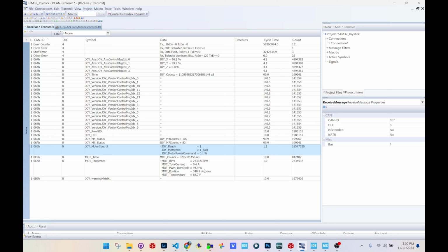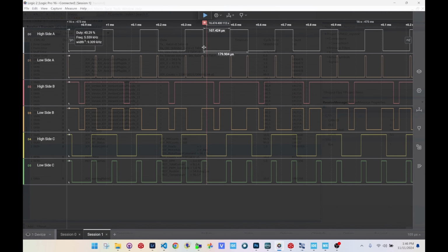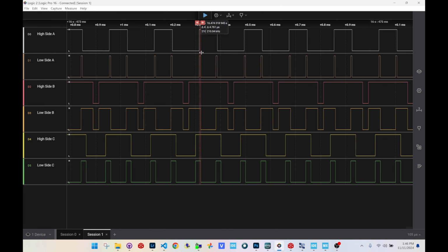I'll now show some of the signals on the oscope that are used to drive the motor. These signals are generated from the STM32H7 and used to drive the H bridge. These PWMs are generated from the timers within the STM32H7. I use these timers and PWMs in order to generate 3 sinusoidal signals. These are used to drive the 3 motor legs according to the rotor position.